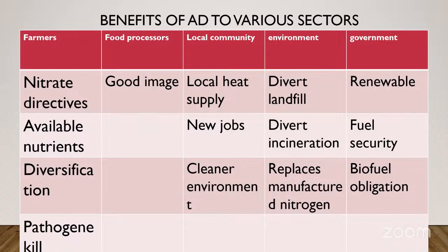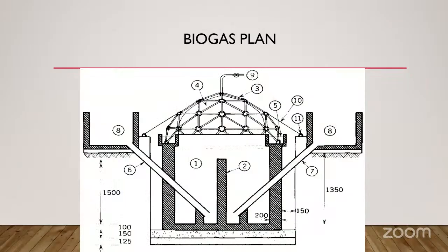So now let's see how we design this biogas system. The biogas system has two chambers, chamber 1 and chamber 2. The first is made to receive waste, which is going to be deposited through this inlet, which is at left, and the outlet, which is at right. The outlet is to collect digester after we have removed the energy, the methane content inside it.